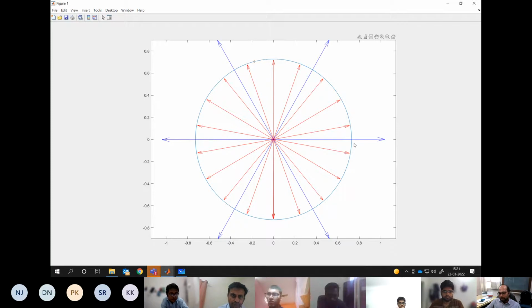As it is rotating from one point to another, we know which sector and which sample it belongs to, and we apply the vectors appropriately based on their dwell time. Here, dwell time we have translated to theta. In response, we are getting these vectors, which you can call the samples of what you have got over here. You understand my point?